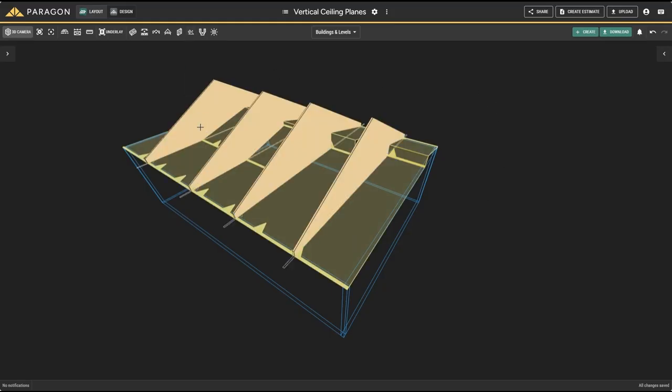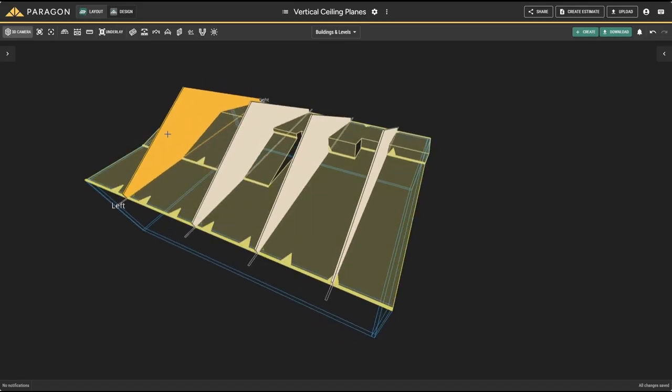Example 1 has a flat section that transitions into a cathedral ceiling. Example 2 has a flat section transitioning to a vaulted section, followed by a vertical step and then another sloped segment taking us back down to the standard height bearing. Examples 3 and 4 are similar in that the bottom chord profile is flat, then steps up to intersect with a sloped segment that returns down to the standard height bearing. Let's dig into each example.